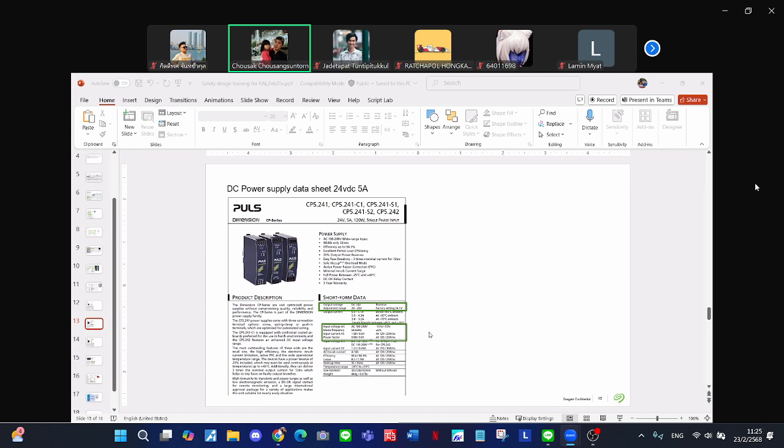It calculates back to power consumption and the current here. And then we choose the same way as the DC done before. 0.75, the closest is one, so I select one for the circuit breakers and use the same cable sizing. And we can copy for the DC one.